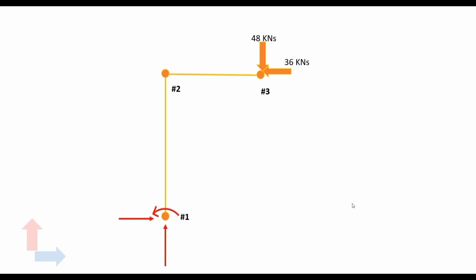So this is the free body diagram of this cantilevered frame model, or of this cantilevered post. Now we have considered the restraints to be in the positive sense. So the global horizontal reaction is pointing towards the positive direction of the global x-axis, and thus it's pointing from the left to the right.